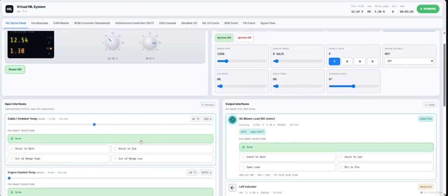During this operation, if any fault is created, for example, a sensor fault shorted to ground, the operation which was happening in the background to make the cabin temperature cool will stop because the fault has been created, and the respective DTC should be logged in the fault memory of the controller.